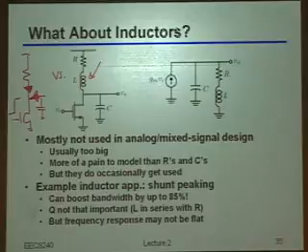Well, if you think about what this inductor does, with inductors, the whole trick is they don't like to change their current instantaneously, right? So by placing that inductor there and again choosing just the right value for it, I'm actually going to force, at least initially, all of the current to come out of the capacitor. Okay? And to the extent that I have more charge per unit time coming out of the capacitor, at least initially, that indeed means I have effectively higher bandwidth than I otherwise would have. Now eventually, obviously, the inductor kicks in and you have to get current flowing through there as well. But that's where the trick comes in, in choosing the right value so that it actually gives you this benefit that you're looking for.